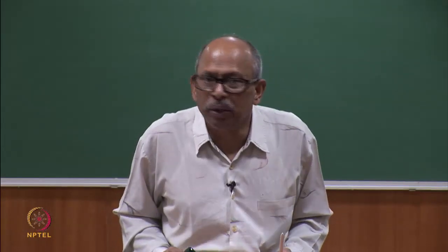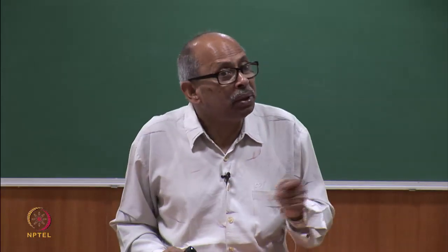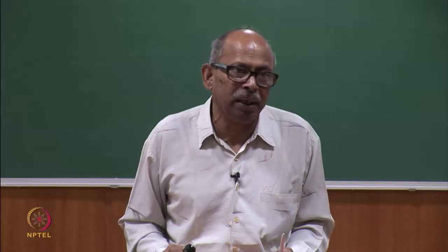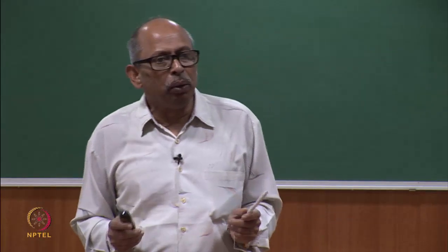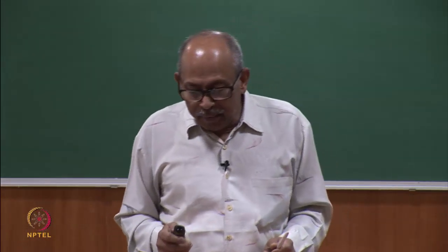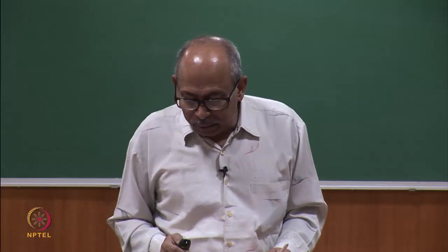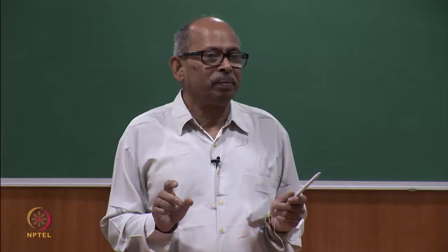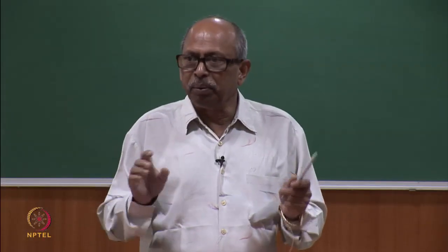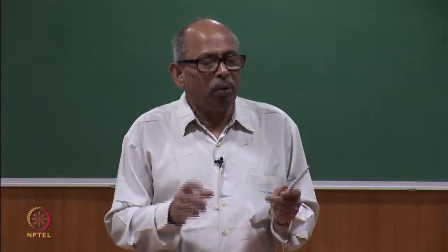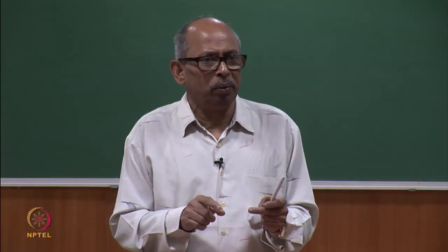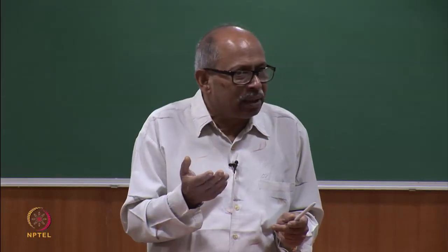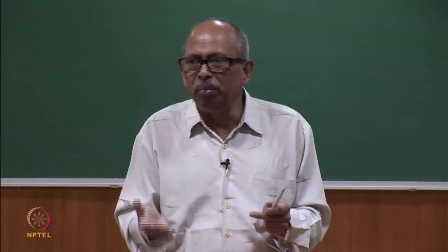First we said how we find out the cover using conventional cover meters, magnetic type, and this is the impulse radar technique, another way. So, you can find out cover. In fact, GPR, as you know, I will come to that. GPR can find out the foundation depth. Depth of foundation you can find out, not profiling you can do. You send a signal through the ground, reflected signal comes back, from the time you can find out.